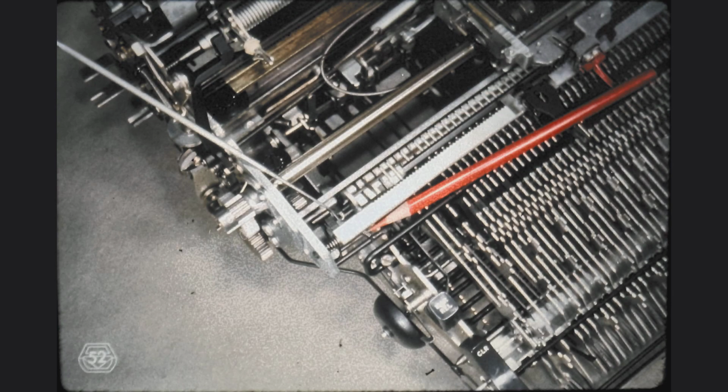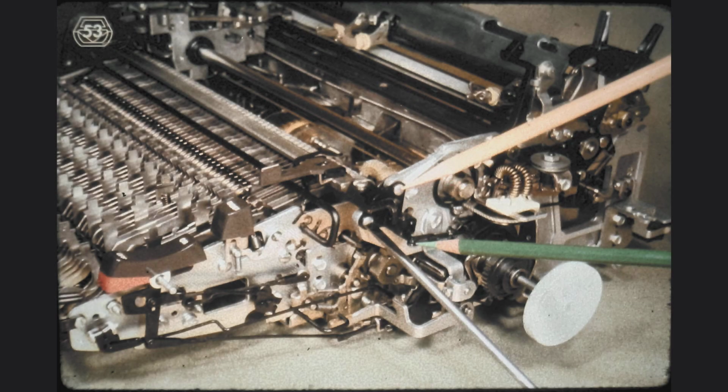Next, disconnect the spring indicated by the red pencil from its anchor spot on the margin rack support plate. Simply leave the front end of the spring connected to the margin release shaft. Now, first we disconnect the carrier return disengagement link indicated by the green pencil. After that, all we have left to do in order to remove the margin rack is to extract the 2 mounting screws for the bracket which holds the margin rack. When you remove the margin rack from your machine, be sure to safely store the compression spring, which you will find at the left end of the margin rack.